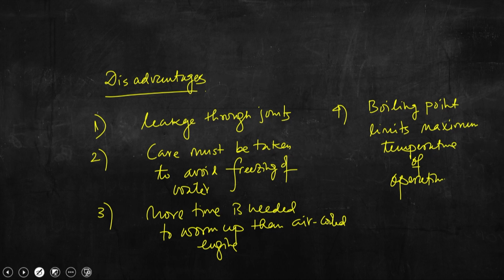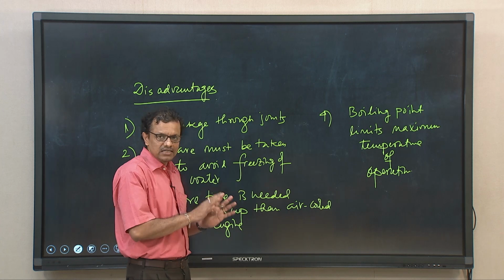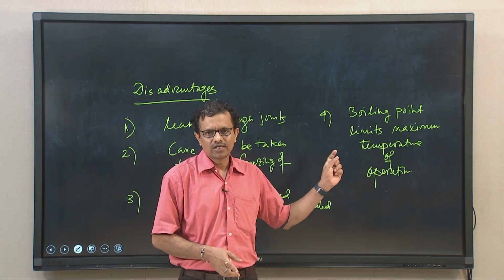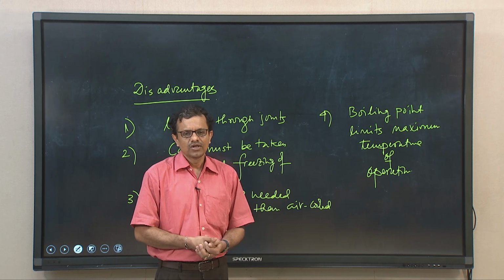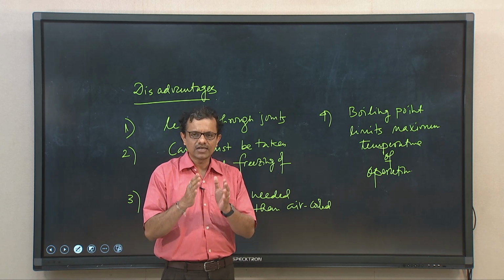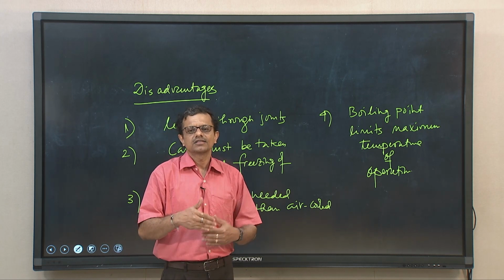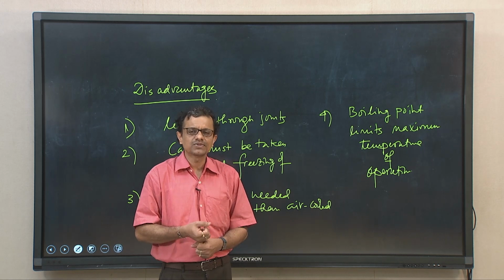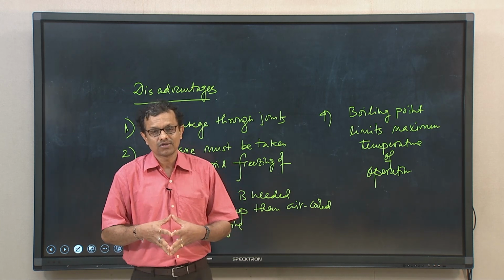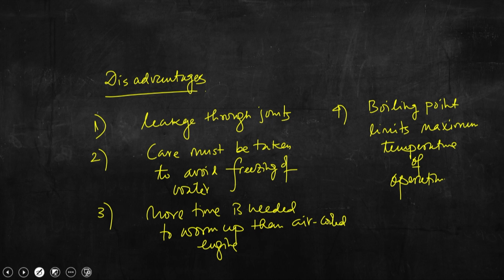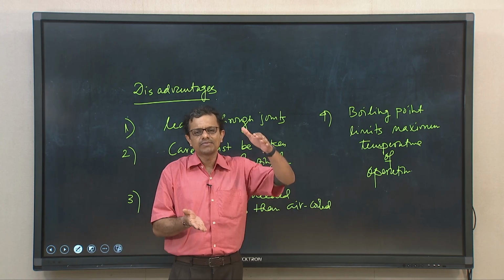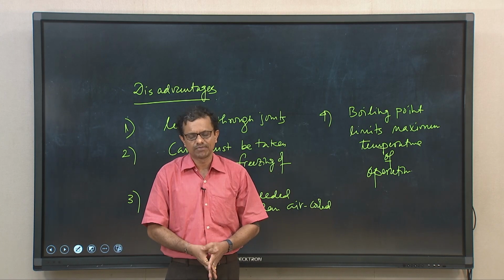So, basically what we have discussed today, this liquid cooled engine has some distinct advantages, also some disadvantages. For the water cooled engine, we have listed a few serious advantages, still we have noticed a few disadvantages. Now, thermosiphon cooling is another system wherein the requirement of an additional pump to supply water from the sump into the engine system will not be there. So, with thermosiphon cooling, we can eliminate the need of an additional pump. So, we can reduce the first time or installation cost, but at the same time there will be some disadvantages because we need to rely on natural circulation. Perhaps you have studied in natural convection that we need to have a certain height difference, otherwise the cooling efficiency will not be that much.